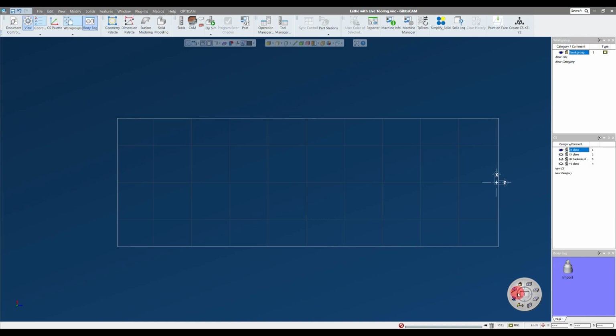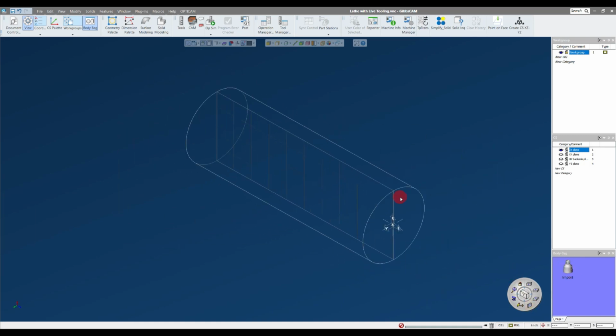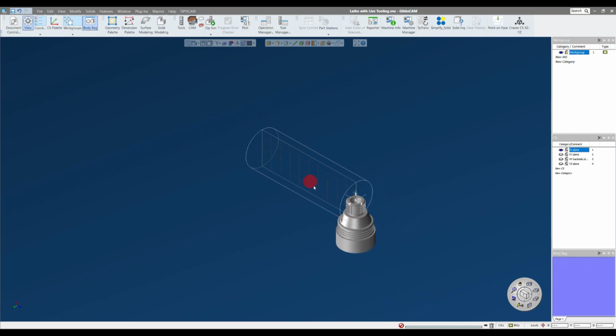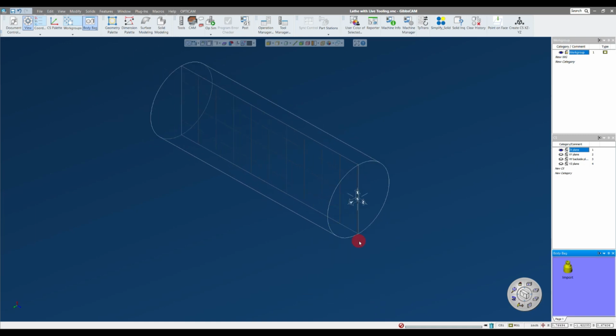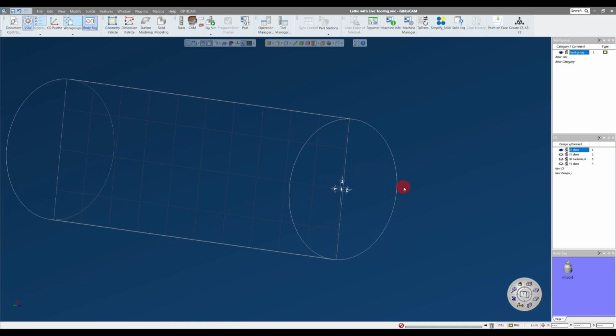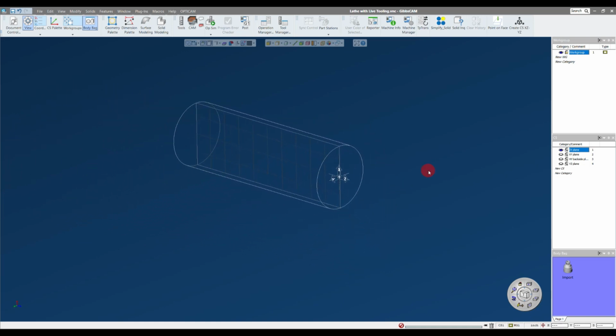I imported into the body bag. And the body bag is somewhat just an alternate dimension where you can store models. So when I imported the model, it came up onto the screen. And if I double click it, it immediately goes into the body bag. So if you end up with multiple models on your screen, say part models, fixture models, stock models, construction models, you can dump those into the body bag and clear off your workspace so it's a little bit more of a cleaner working area.